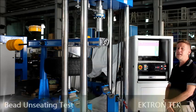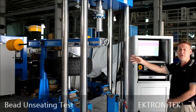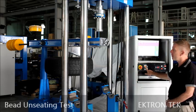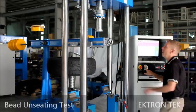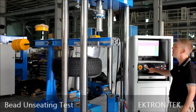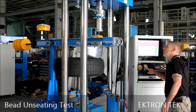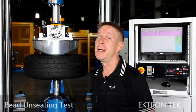The changeover to the bead unseating test is simple and quick. The tyre is removed from the frame, the plunger is unscrewed from the piston, and the machine is brought forward. When we bring it forward, we make sure that the bearing lines up with the center of the piston. Now we have the instrument set up for the bead unseating test.